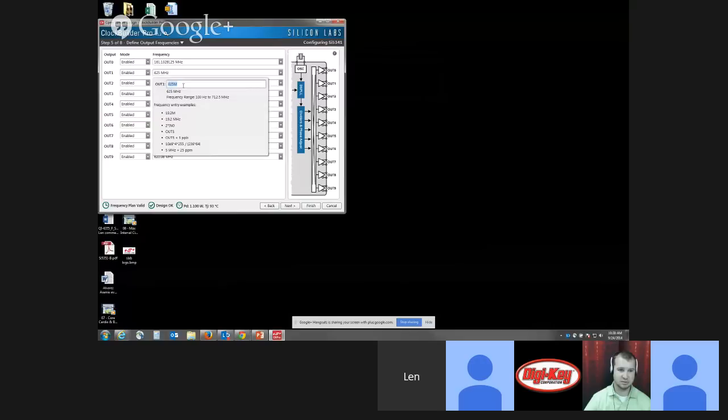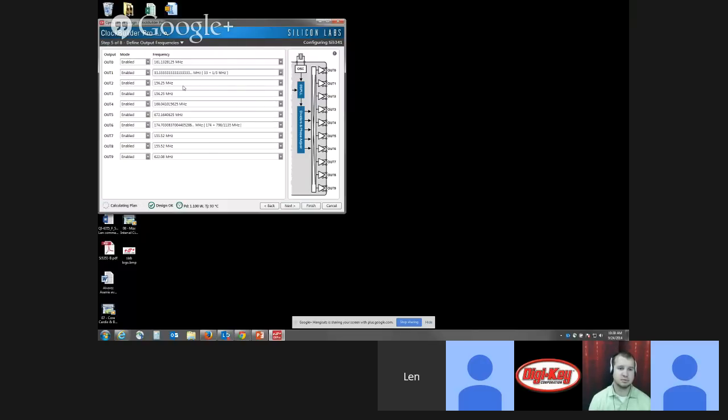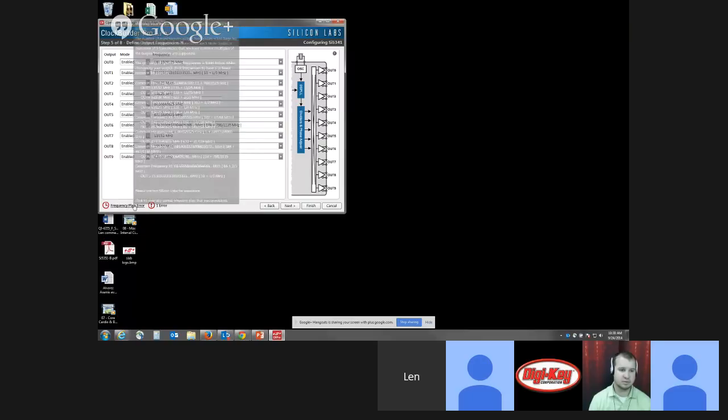I can add mathematical expressions, we try to make this easy. Let's say I don't know how many bits to put in this divider or whatnot, but I know I want 100 divided by 3. You can add mathematical expressions. I can say, hey, you know what? I want this clock to be 1/2 of the output number 0 clock, and it'll figure that out for you. And if you're doing crazy stuff, it'll say, oh, you did an error. You did something crazy here. But anyway,